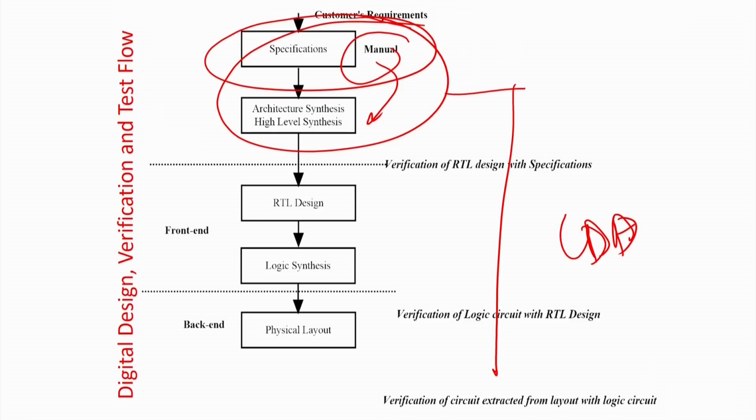because you know your design specification: what speed you have to achieve, what the power requirement is, what the area requirement is, and what price I am going to put in the market. Say that I can design a very super fast adder, maybe in very low power, and with all other requirements, but then the cost of the chip may be very large and you will not have any customer. So you have to think based on the price and optimize all the other parameters: what is the minimum amount of blocks I require to solve the problem. So here there is some design optimization which I have to do.